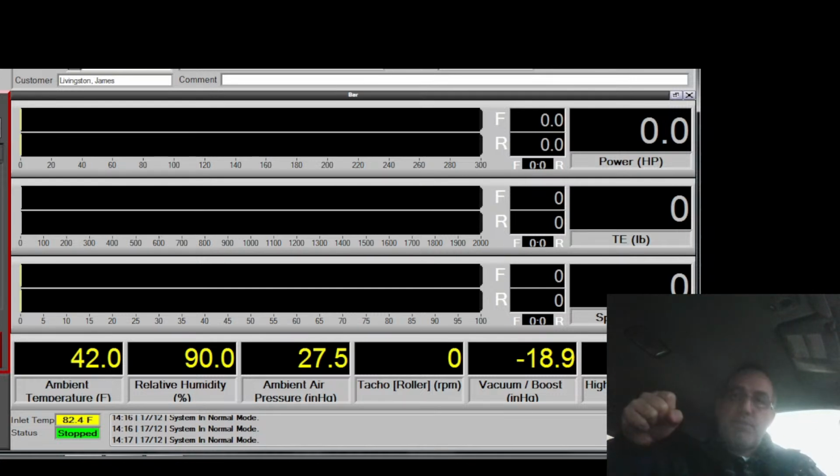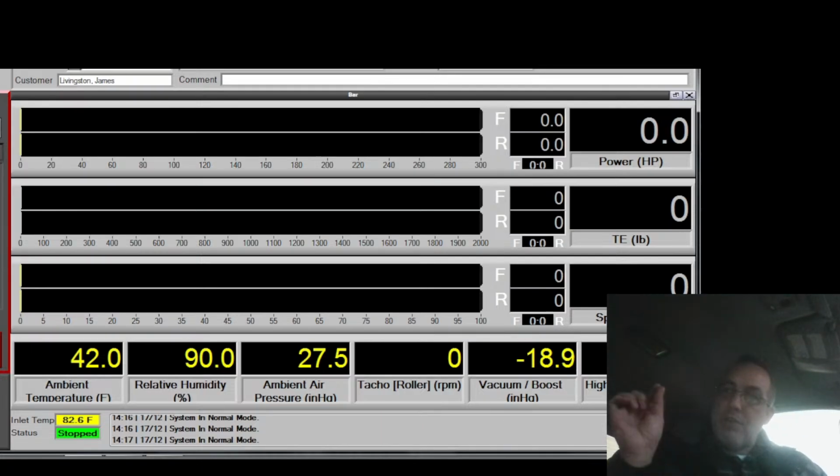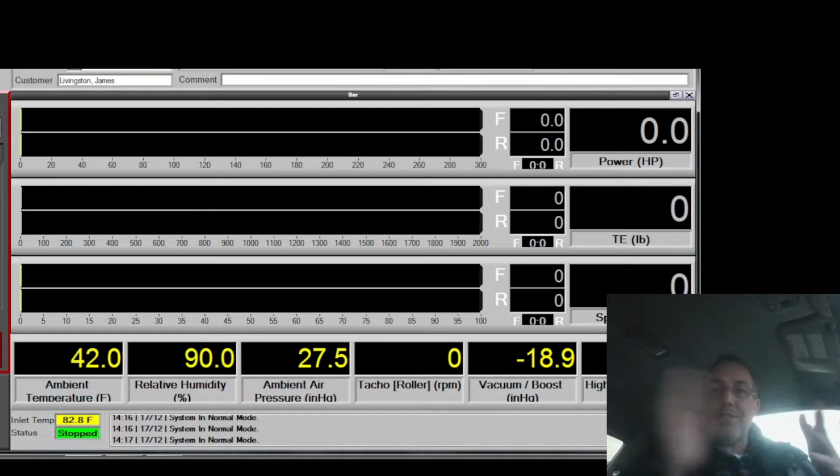I'm putting so much pressure on a lever arm, so I got 10 pounds times 2 feet. It's the same deal. So if I wanted to do a seesaw, which is, again, like center of gravity on an airplane, I do the same thing. I could have 10 pounds at 2 feet, 20 pounds at 1 foot, right? And my center of gravity, I got this one be -1, this would be +2 as far as the distance is concerned, and they end up zeroing out, and the item would be in balance.